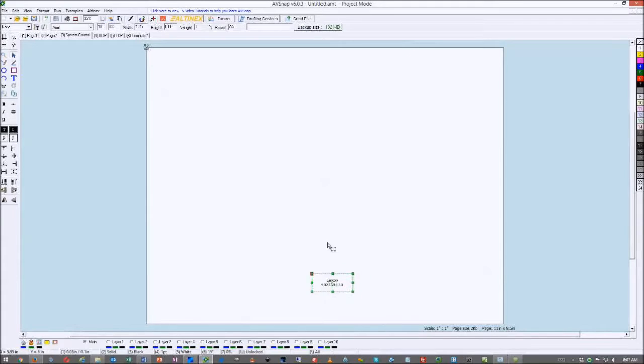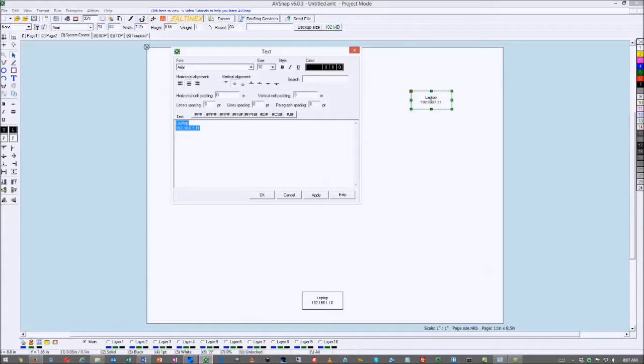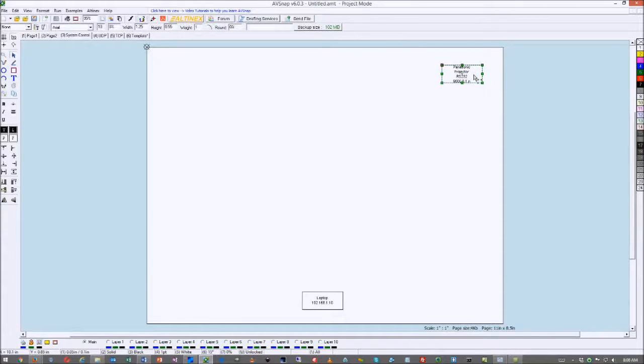And then I'm going to put some components here. So the component could be a projector. So I'm going to put Panasonic projector. And I'm going to control it through RS-232. So I'm going to put RS-232. And I'm going to put immediately the baud rate, 9600, 8, 1, okay? So you can see in the diagram, I will have enough information to understand what I'm doing.